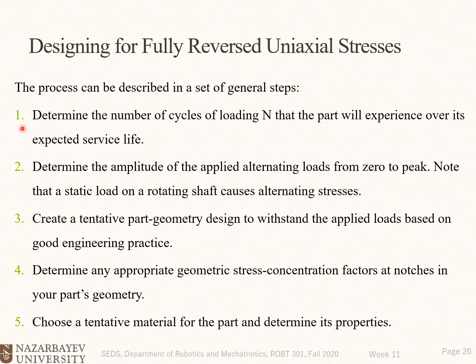First, determine the number of cycles of loading N that the part will experience over its expected service life. So for example, we have a shaft. How many rotations will that shaft go through in the whole of its life?